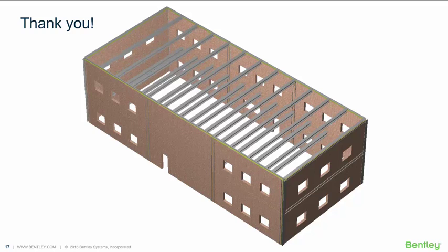What material should you model masonry walls with in structural system? You can use either the type other material or concrete. I think generally in our demonstrations we've modeled them as type other just so that you know the difference. You know that it is in fact a masonry wall and not a concrete wall, but I think either one can be imported into RAM elements.